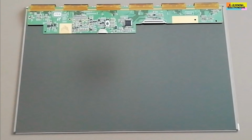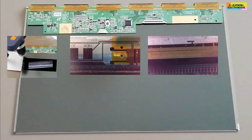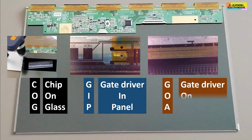Some screens, especially those of the latest generation, do not have a COF gate driver on the sides. This does not mean that the screen does not have a gate driver. On the contrary, the chips exist and they are integrated directly into the panel, as for the TFT transistors or storage capacitors. This technology is currently favored in the manufacture of screens and it has several names. We find COG, which means chip on glass, GIP for gate driver in panel, or GOA for gate driver on array.